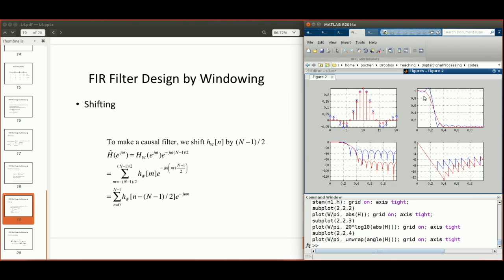That's often the case, actually. If you look at lots of different filters, that's often the case. If you want fewer ripples, you usually have to make the transition band wider in order to reduce the ripples. And that's plotting the amplitude spectrum in terms of dB, a log scale, and you can see this. The red filter is actually better at suppressing the high frequency content. It's a low pass filter. It passes the low frequency band and suppresses the high frequency band a lot better than the blue filter. And again, the phase is still linear for the pass band.